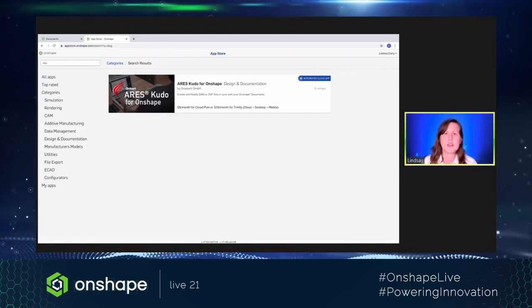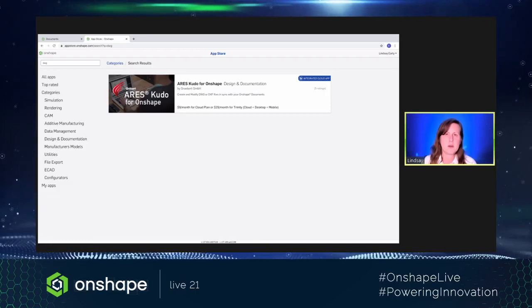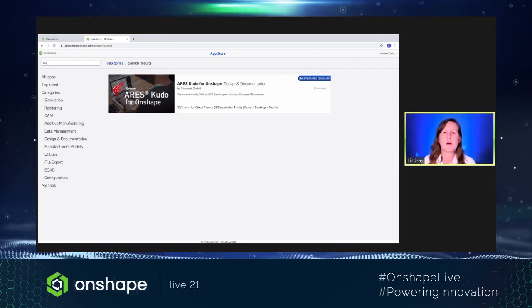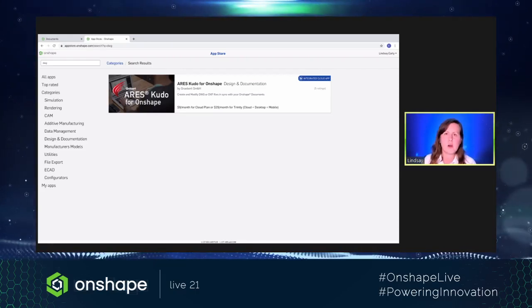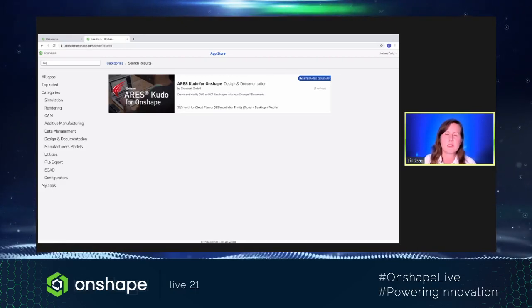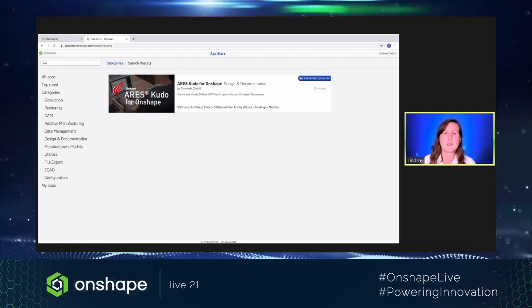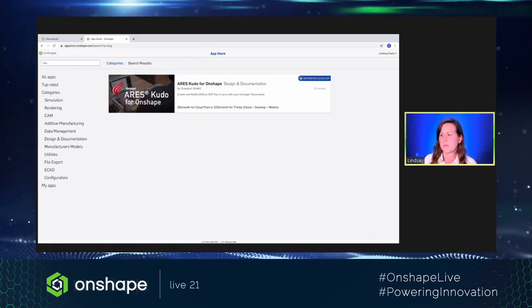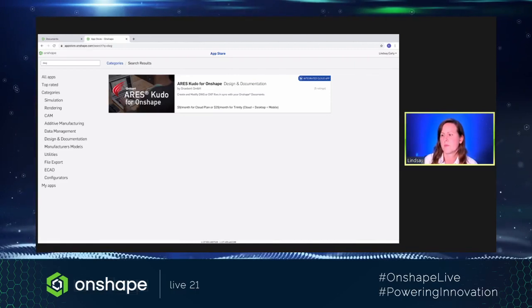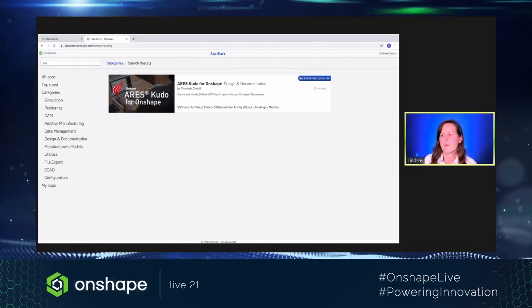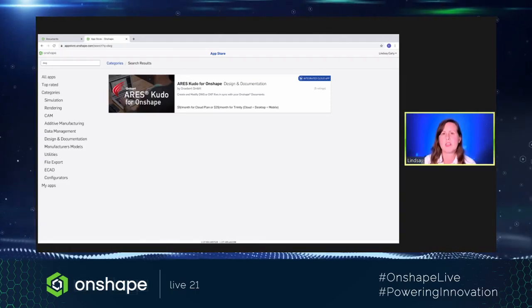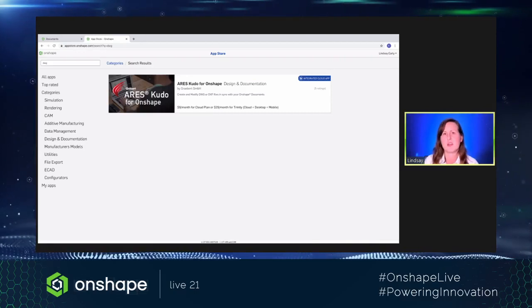I would just make a folder and put each differentiated part in its own document. The reason I say own document is because if you have several parts all in the same document and they're all linked to all kinds of other assemblies, then that's just more assemblies that you need to update needlessly if some part in some tab got updated. So it's better to keep them separate so that those links only get updated when they need to. I usually just create a folder and share that with the whole company and then put each of those documents in there and you can use them as just regular parts.